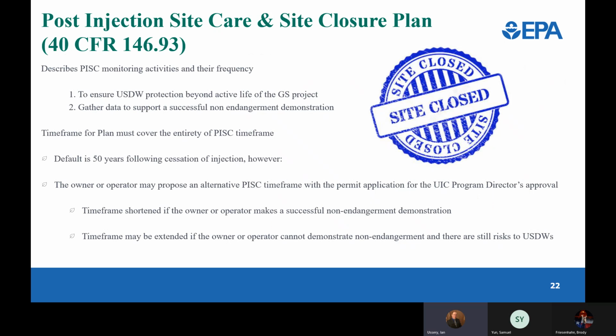Next slide, please. Now, for the post-injection site care and site closure plan, or PISC, this basically outlines the monitoring strategies and how non-endangerment of USDWs will be ensured throughout the post-injection site care phase of the project. This is to confirm that the applicant proposes to use proper plugs and cement in all monitoring wells and that they are of suitable construction and at appropriate depths.